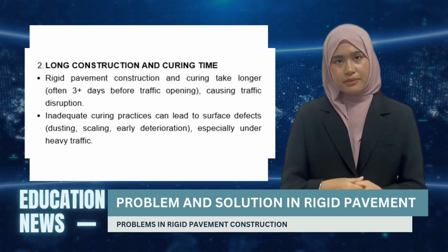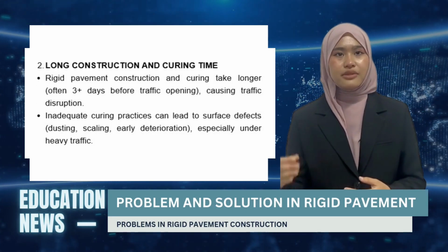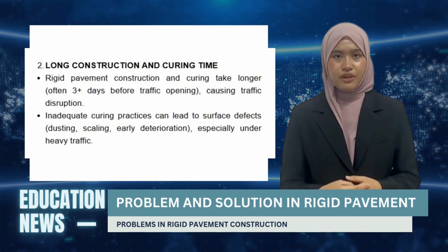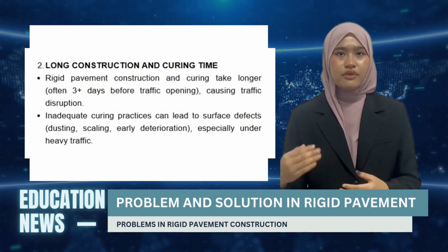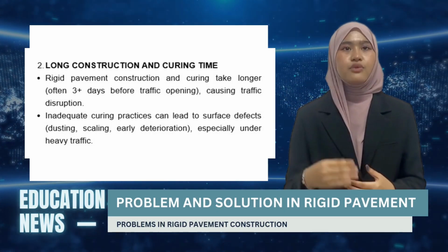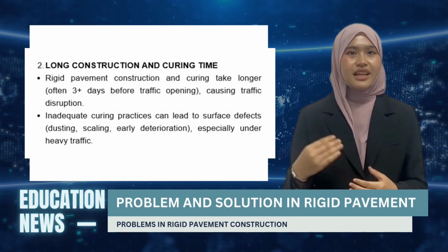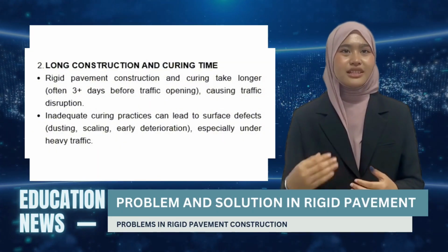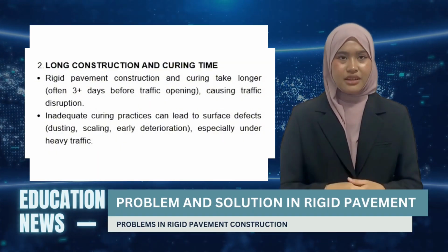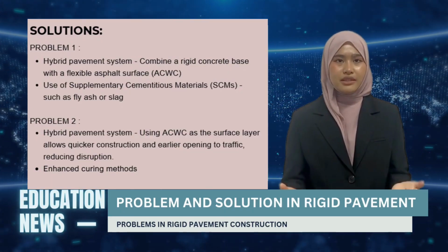The second problem is the long construction and curing time. Rigid pavement normally needs several days before it can be opened to traffic. This often causes traffic congestion, especially on busy expressways. If curing is not done properly, the concrete can develop surface defects like cracks and early damage, which reduce its durability. Okay, now I will move on to the solutions implemented to overcome them.